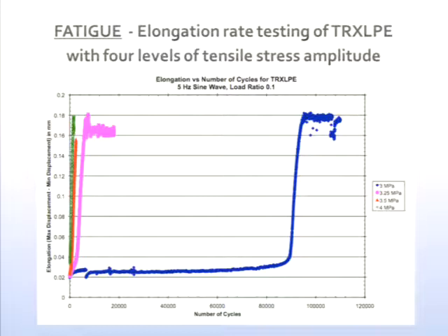At 3.25 megapascals, it occurs much earlier. At 3.5, yet earlier, and at 4 megapascals, it occurs like that. I mean, this might appear to be instantaneous, but of course it's actually several tens of cycles, perhaps even several hundreds of cycles. So this material is failing under fatigue at stresses which are starting to approach the region that we calculate from our mathematical model.